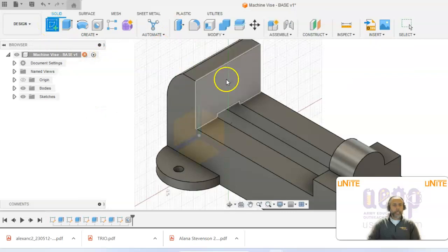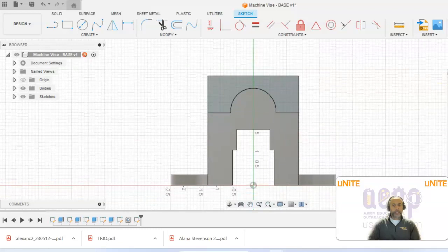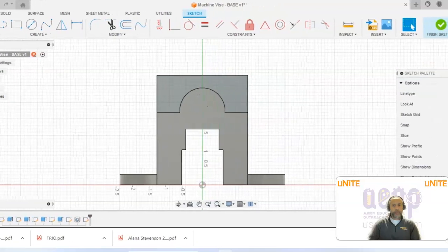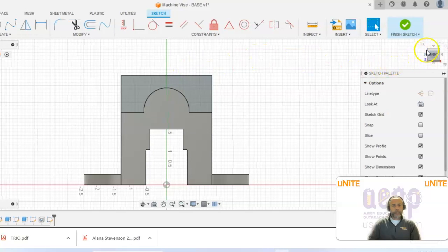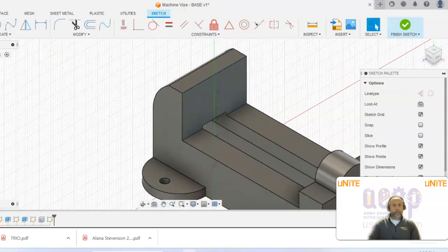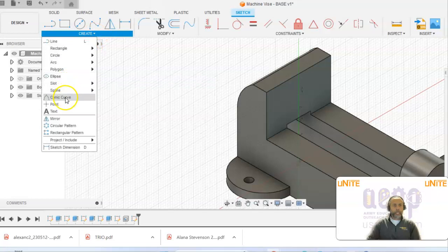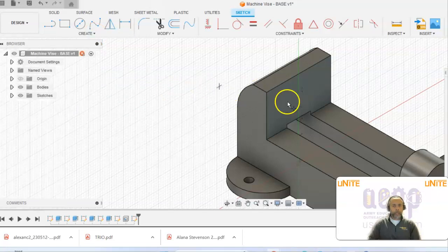So you go to Create Sketch and select the surface. If your part orients facing that surface, you may need to select the corner of the view cube in order to reposition it. You can go to Create Point, and we will create 2 points on the surface that will represent the center of the holes.